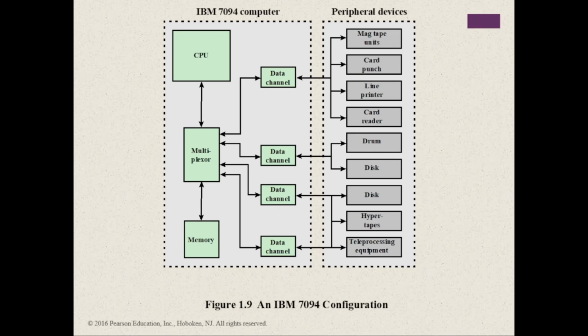The control unit fetches two adjacent words from memory for an instruction fetch, except for the occurrence of a branching instruction, which is relatively infrequent, perhaps 10 to 15%. So this means that a control unit has to access memory for an instruction only half the instruction cycle. This prefetching significantly reduces the average instruction cycle time.